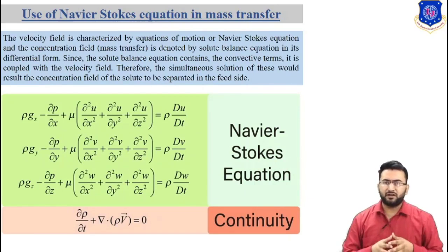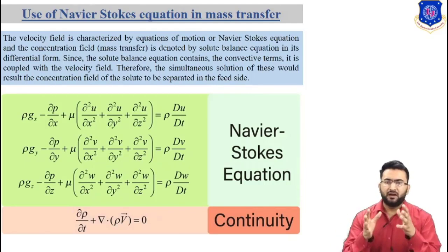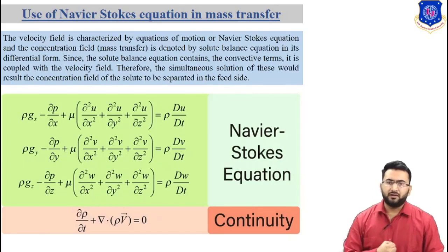In most practical industry scale, the separation occurs under a steady state condition. Under such a situation, the feed and product phases flow past each other. In almost all cases, the flow directions of the two phases are countercurrent in nature in order to have a higher driving force.